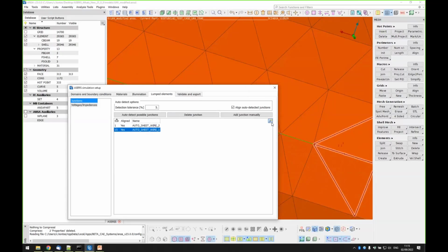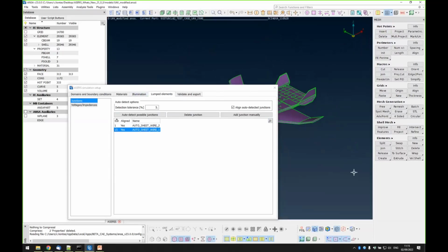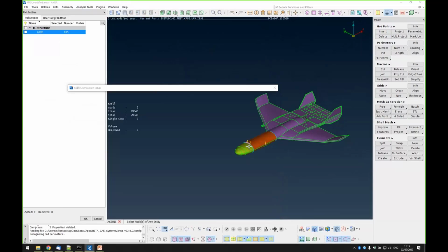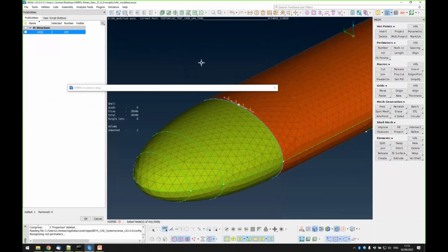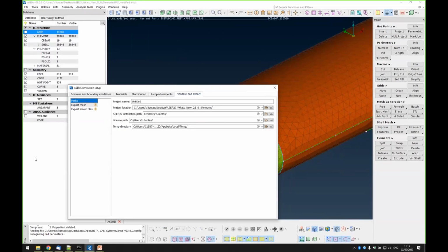Okay. So finally, we want to define some excitation for our antenna, or else it will not radiate. So let's define a complex voltage source on my antenna in the middle. Okay. Let's see. Yes, this is it. Let's say it radiates at 1 volt. And finally, let's save our model. Okay, now let's say this is the name. Let's put the correct installation path and the license path.